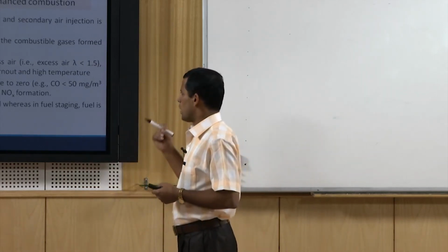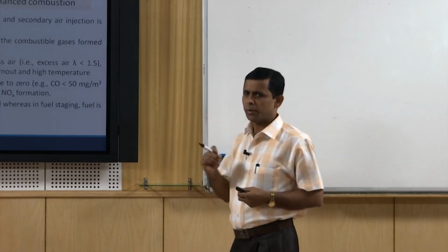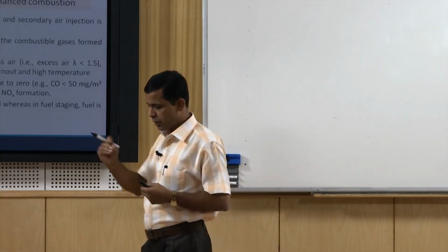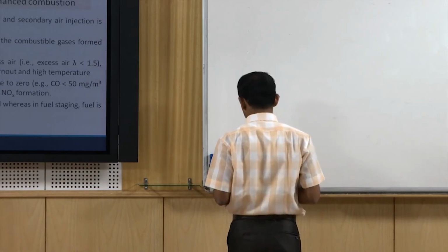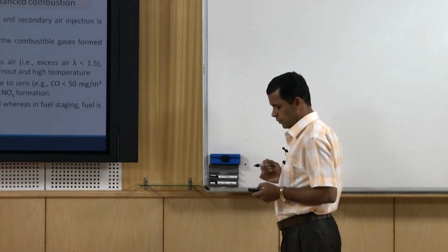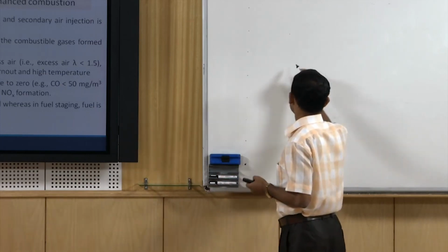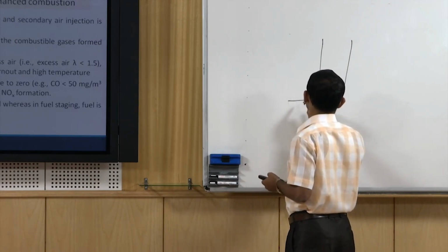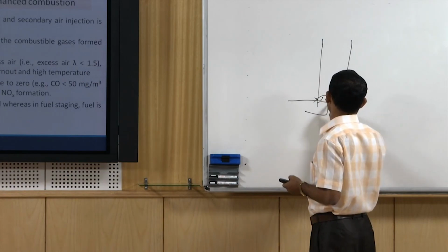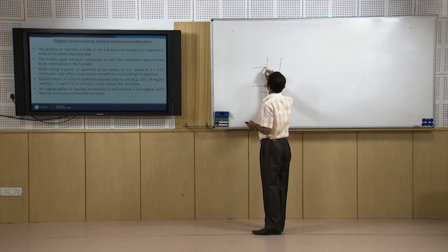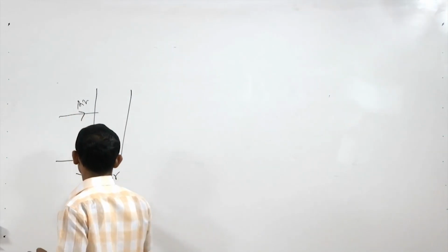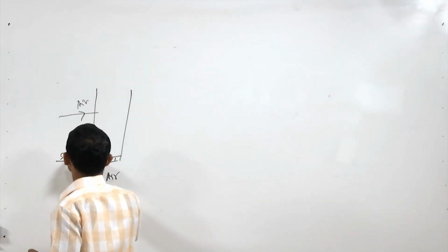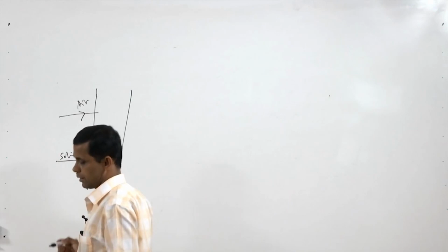Therefore, to achieve this, the minimum or optimum excess air, people tried in the process design part. Say if we have one incinerator, we can feed the fuel or the solid waste and oxygen in different ways. So, some solid waste is fed here, so we can get oxygen or air, and here again secondary air is given. So, primary air, solid waste, and this is secondary air.